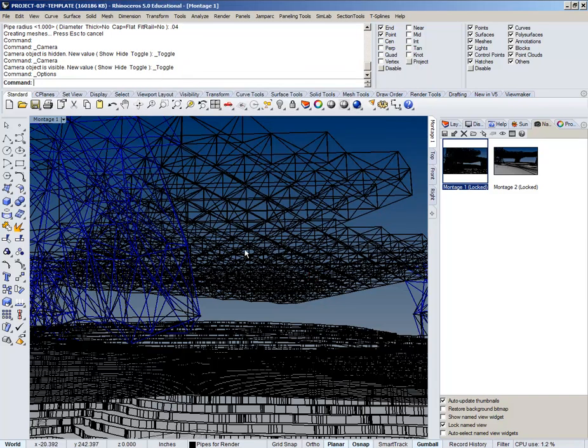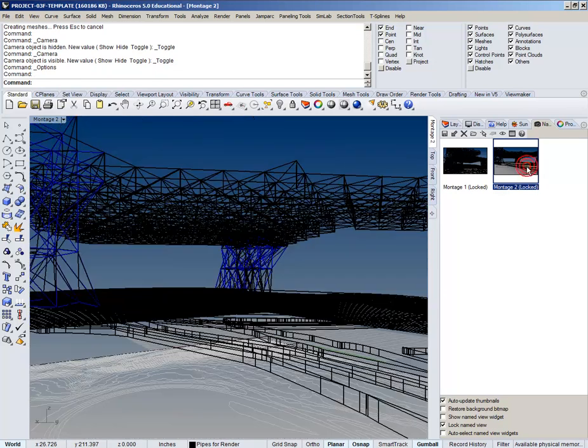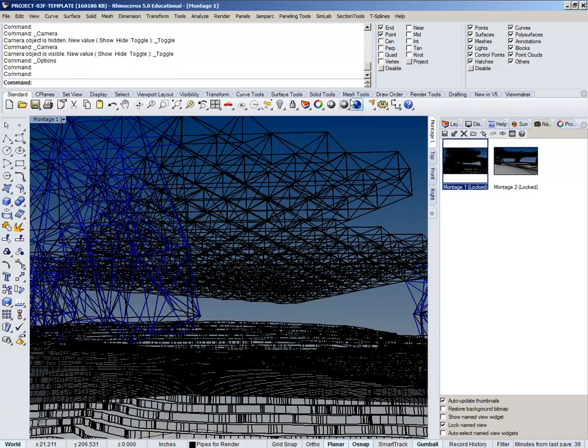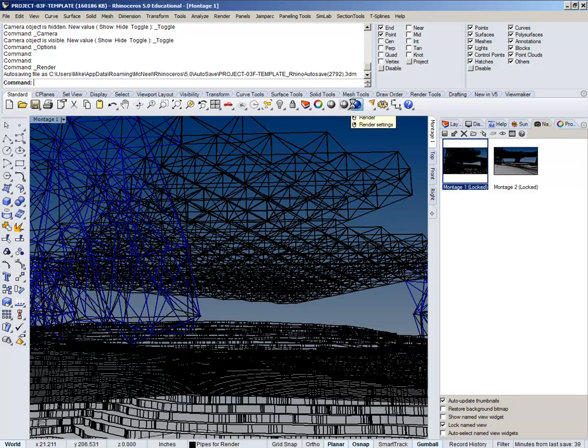And you don't have to worry about the curves too much. You do want to make sure that two things are on: your topo's on and your pipes are on, because if you don't have the topo, you're not going to know what's blocking the land and how it's sitting on the site. So you want to include that. And for this view, you want to be able to get the cast shadows onto the ground that this sun produces. So then at that point, you're just going to hit render.